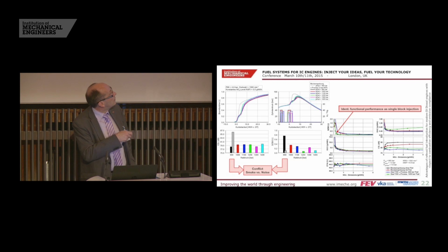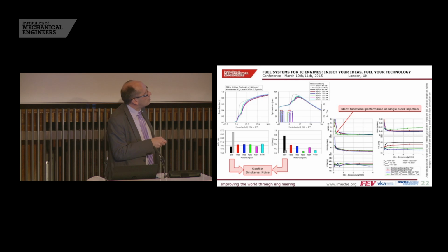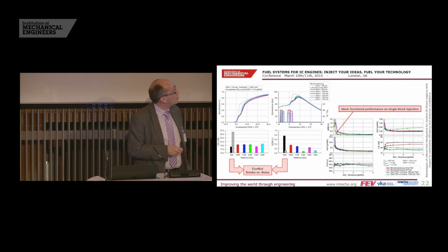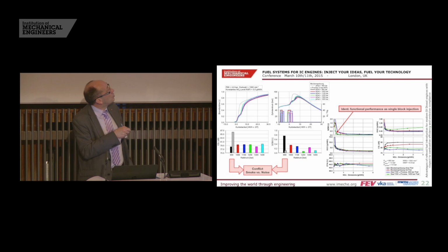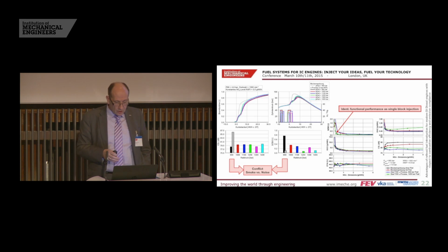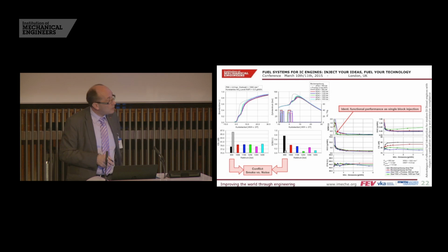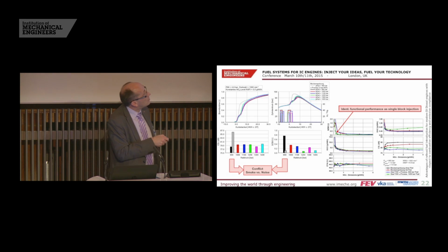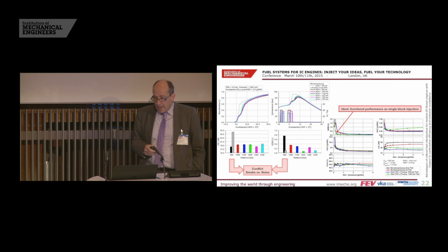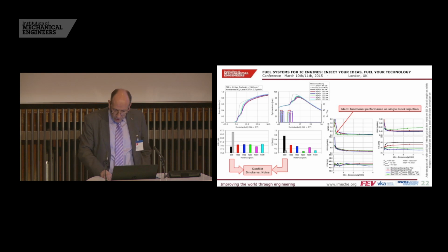And here you see then the investigations according to different types of settings. And you see finally at the end of the day, there is a potential to use the higher rail pressure which is available with an acceptable level of noise by a modulation of the fuel injection as function of this digital rate shaping. And in the following EGR sweep, you see that here you can gain more or less the same functional performance as you would have with a single block injection.